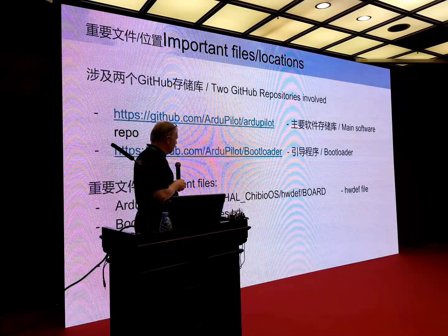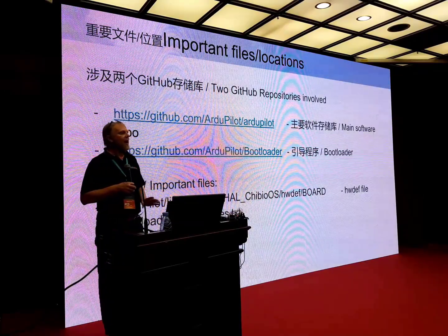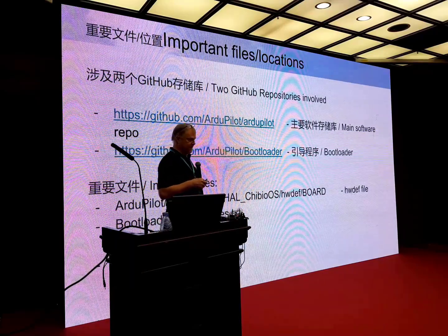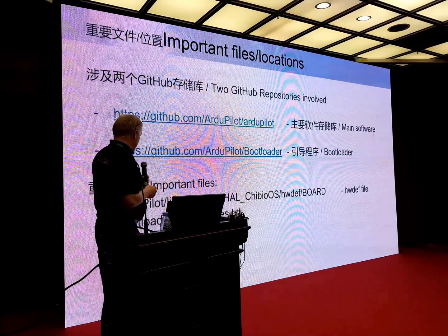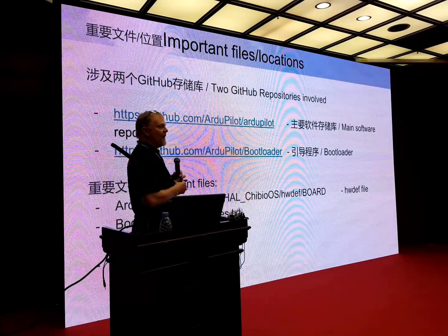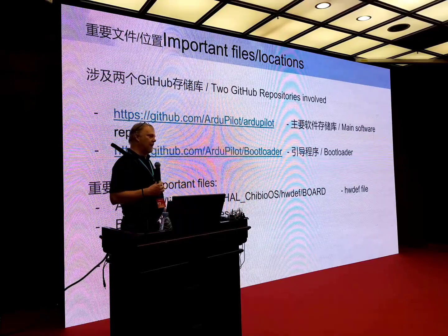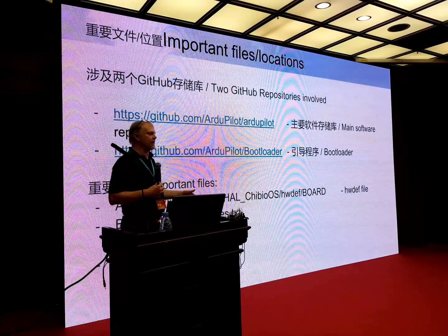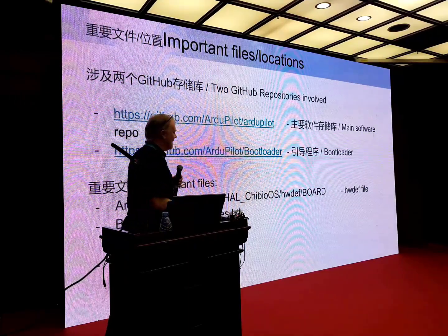Then on the bootloader, what I was talking about earlier, we have basically one single file that we need to take care of. It's the board_types. I'll come to that one a little bit later. And of course, when you're building your hardware, you're building your software, they are going to be under ArduPilot build and then a board name. There are going to be bootloaders, there are going to be the real firmwares and everything like that.